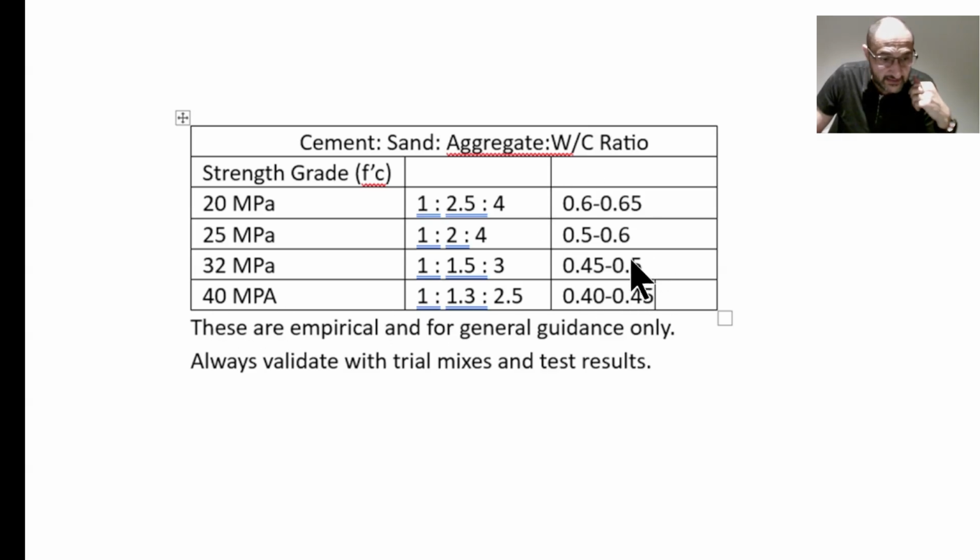So we have to make sure that we're careful with the amount of water we put in the mix. Now, these values are just empirical, and the values that I have here are just for general guidance. So always validate this with the trial mix and the test results that you get on site.